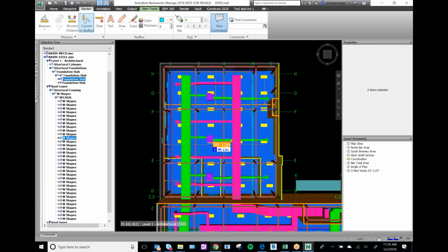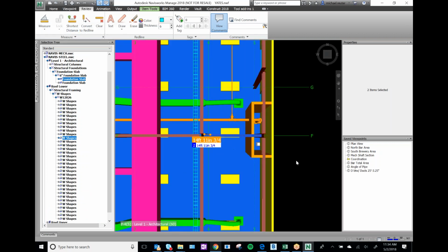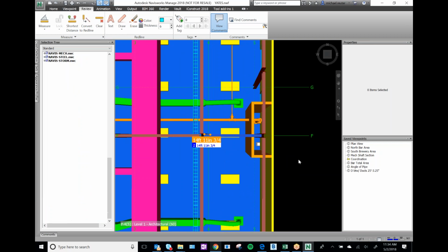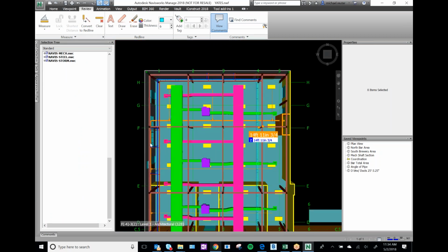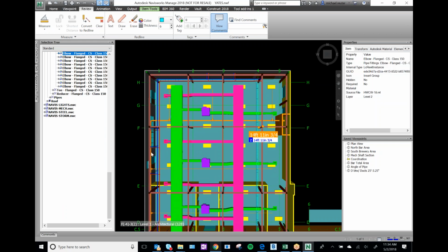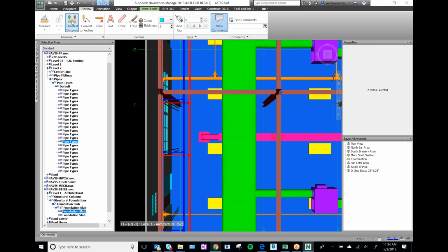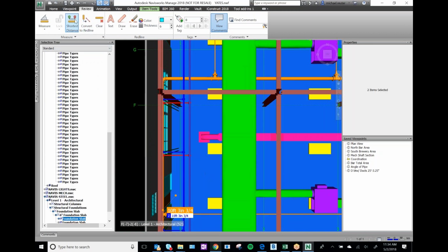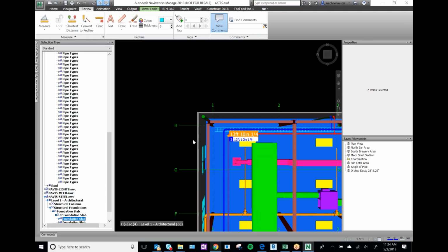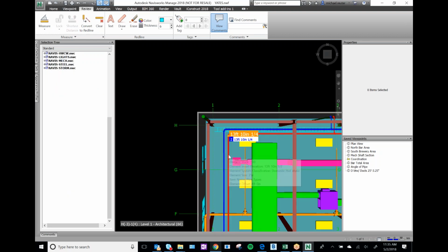This beam is 14, 11 and 3/4. It's a weird elevation. Okay. So this pipe, got it selected. Hit Control, click, select the floor. 10 foot 3 3/4. This pipe, the floor, 13, 10 1/4. So if I roll over it, let's see if the quick property tells me the same. 13, 10 1/2. So I'm pretty close.